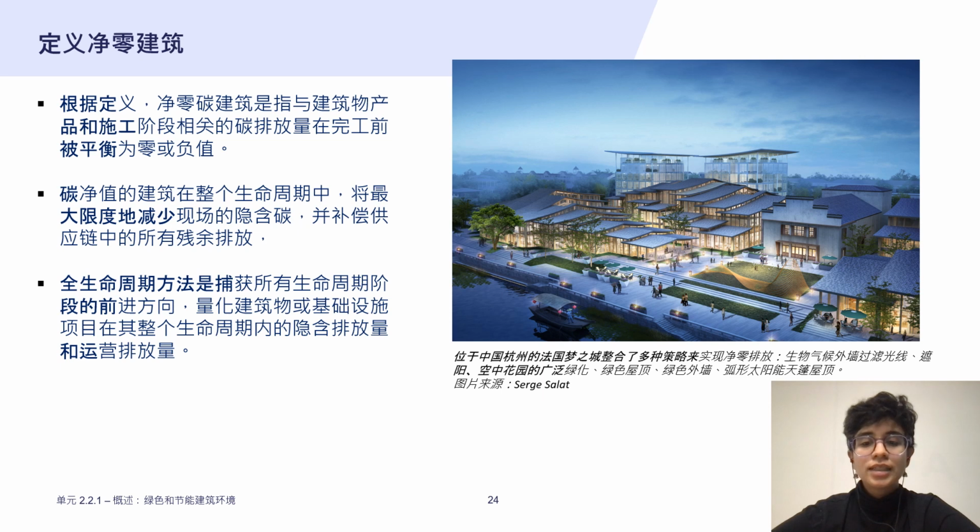Historically, design decisions regarding material choice, material volumes, building lifespan, etc. have typically been made with a heavy focus on operational emissions and aesthetics without considering the embodied emissions. Moreover, in many cases, increase in renewable energy production and existing energy efficiency regulations means that the operational emissions of buildings are already set to decrease. The neglected embodied emissions are set to rise and should be pursued as part of the whole life cycle approach